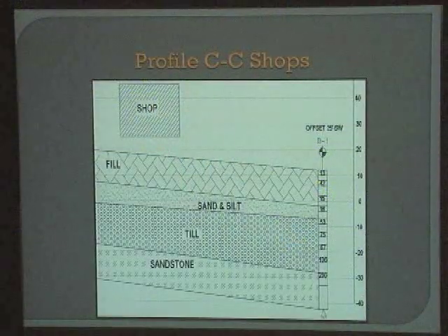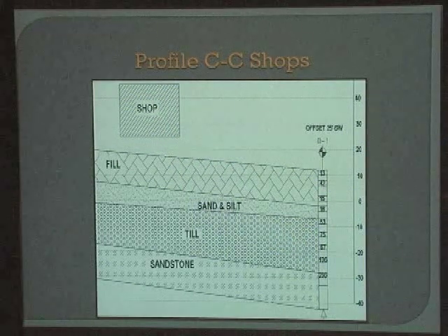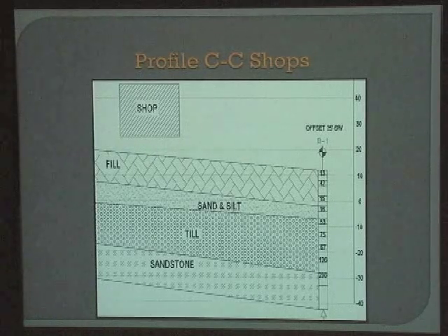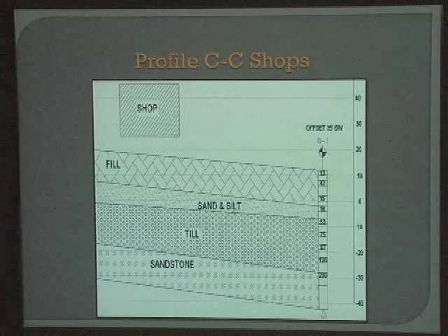And beneath that, we had a pre-existing layer of fill about 10 feet down, which contained inconsistent densities. And from this, we determined that it was inadequate to support our loads. Beneath this was a small natural sand layer containing some silt or gravel, which was then supported by dense glacial till and sandstone or bedrock.